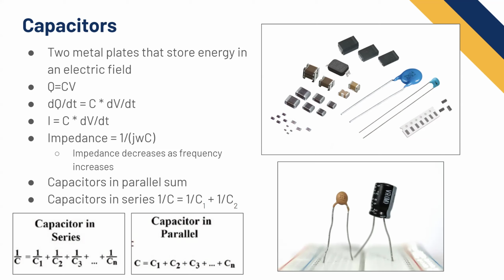That one actually has a fluid inside of it that helps with the dielectric. Something important to know about those ones: they have etched lines in the top so that if you overvolt them, they will blow out of the top and projectile. So make sure you don't overvolt those ones, and be careful of them when you're working with them if you aren't sure of your voltages, which you should be sure of beforehand. Just keep in mind, these are usually power components a lot of times, so they can blow sometimes.